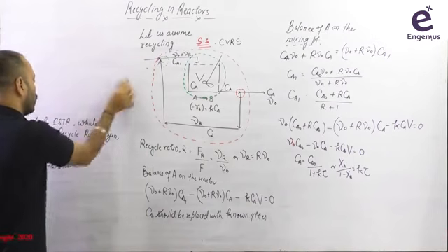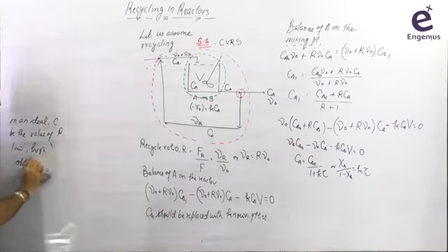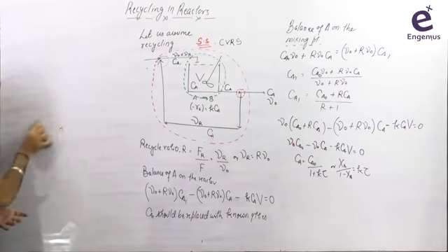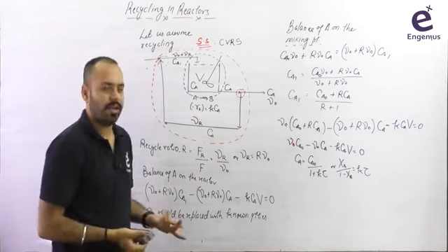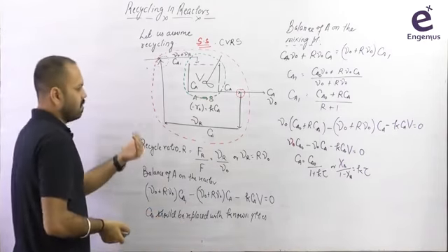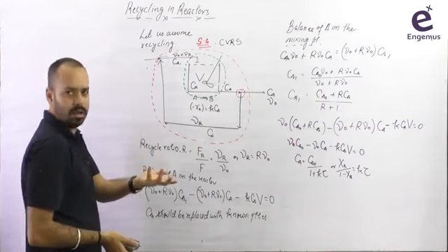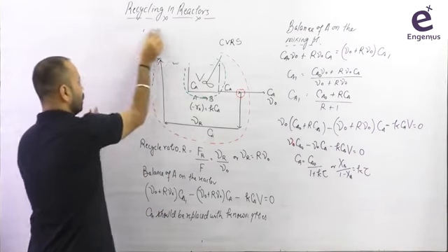And when we talk about recycle reactor in reaction engineering, it is most of the time PFR with recycle, because I proved here right now that there is no meaning of CSTR with recycle. We are not having any advantage or disadvantage also. Of course, if you are doing recycling in a CSTR, it may add up to the cost of pumping and recycling. So there is no advantage of recycling in a CSTR.